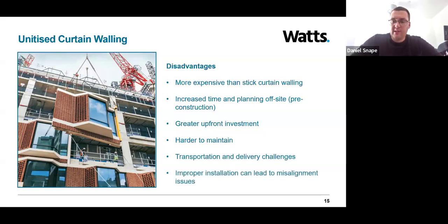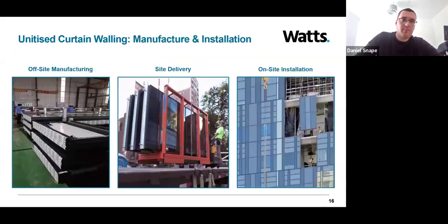And last but not least, as with anything in construction, improper installation can lead to misalignment issues and various defects, such as affecting the weather tightness of the system or the acoustic performance. So, as with everything, the quality of the outcome is only as good as the quality of the workmanship during the installation period.